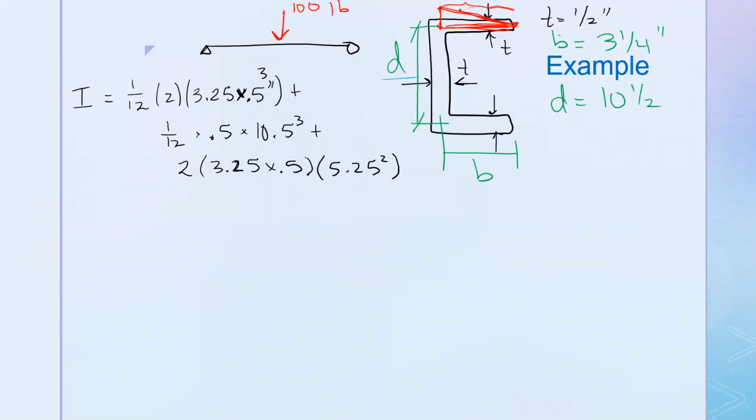So the Ad squared, in the end, is a measure of the shape's resistance to bending about this axis. And that axis is located at the centroid. When we look at a particular component of the cross section, for example, if we're just looking at this shape here, the 1/12 bh cubed mathematically gives you its resistance to bending about this axis. But if you want it about that axis, the way that you get that quantity is with the plus Ad squared.